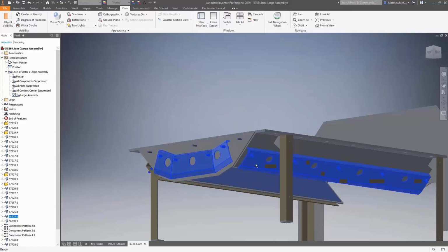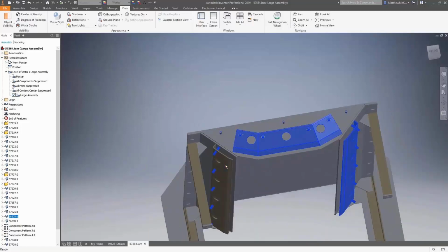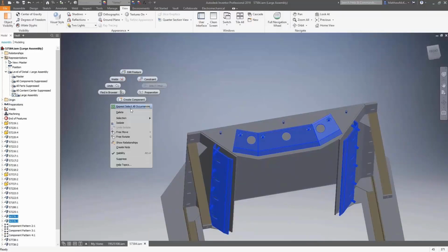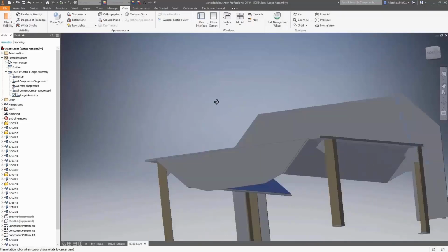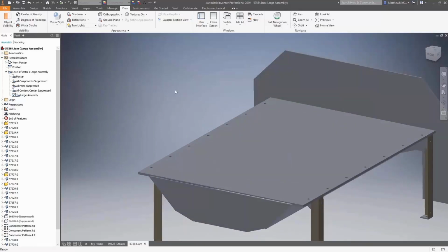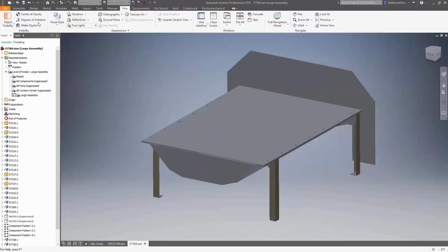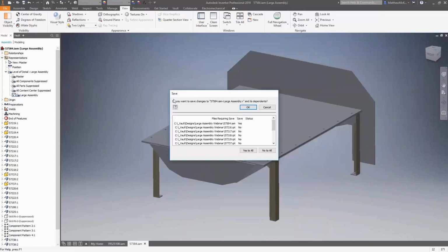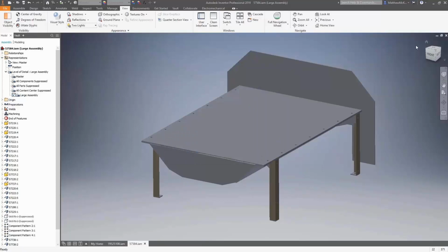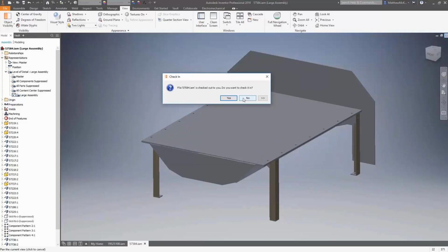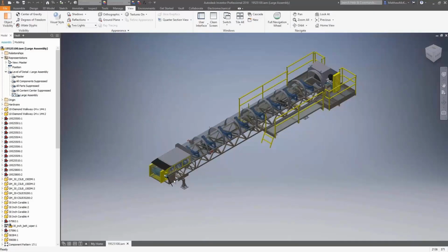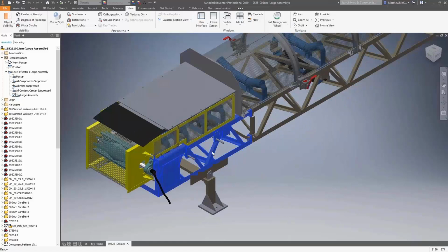And then we're using some of our selection filters to then run around and find parts or components within our design that we can suppress. Now, remembering, by suppressing the component in a level of detail, we're actually removing it from memory, or we're avoiding it loading into memory. In this instance, we need to save it. It's critical. If you don't save it and you switch to a different level of detail, it won't be retained.